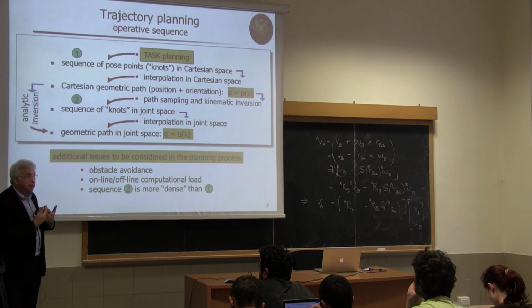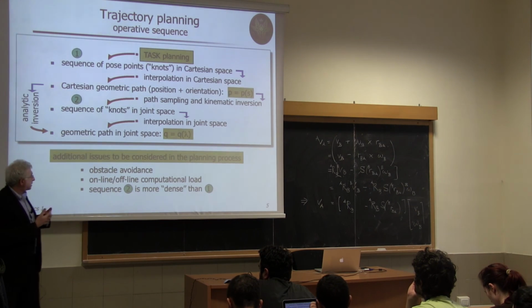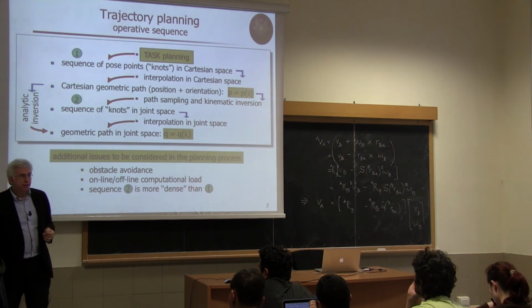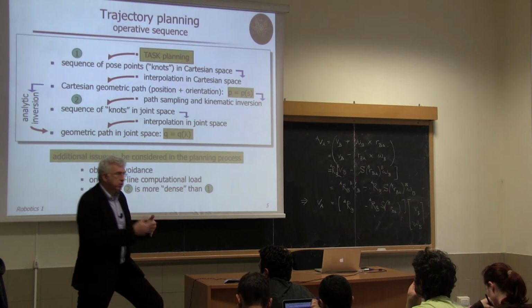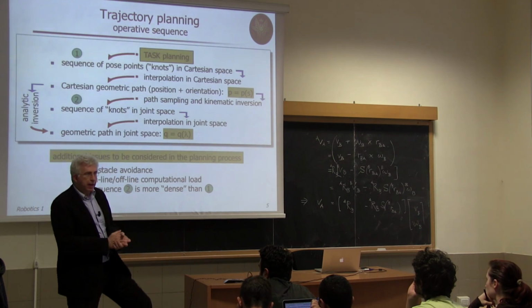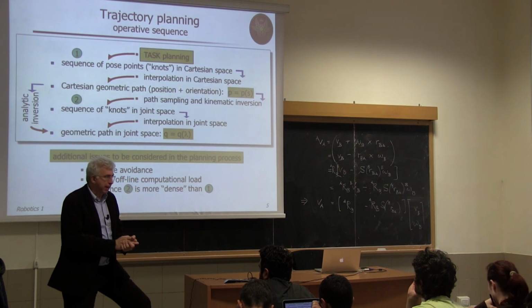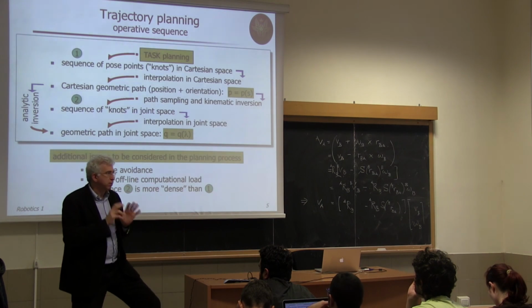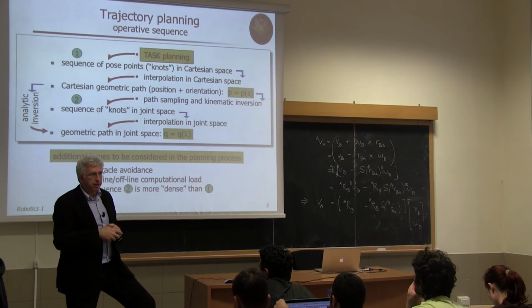In the joint space, the other consideration which is important at this planning stage is what you compute offline and what you compute online. So whatever can be done in advance and whatever needs to be executed online. So for instance, if you rely on Cartesian planning, since motion is always executed in the joint space with your actuators, at runtime you will have to invert things.